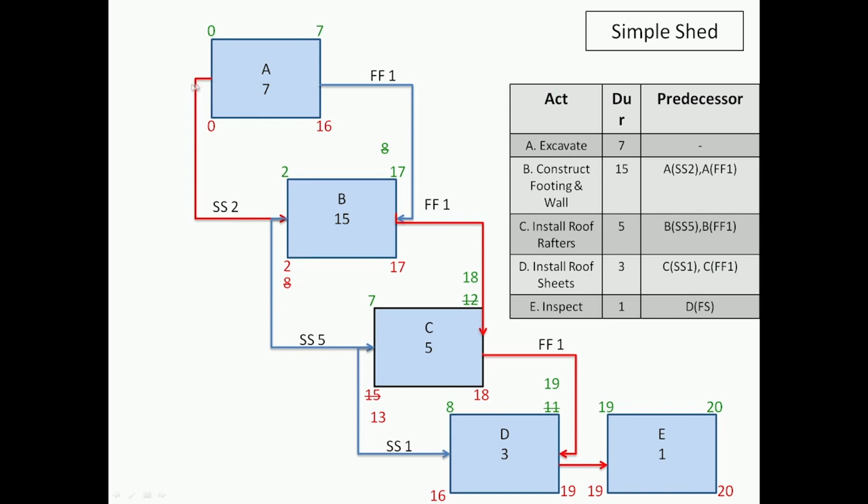From the network perspective, it might show that just start A and then everything can take care of itself, but that is not how it is going to work, and you will have to really know the physical layout and how the progress of A, the work front for A, has to come to B. So that work front progress has to be planned and that detail has to be taken care of. Just because we have this relationship, we cannot assume that the event here will take care of all of the network.